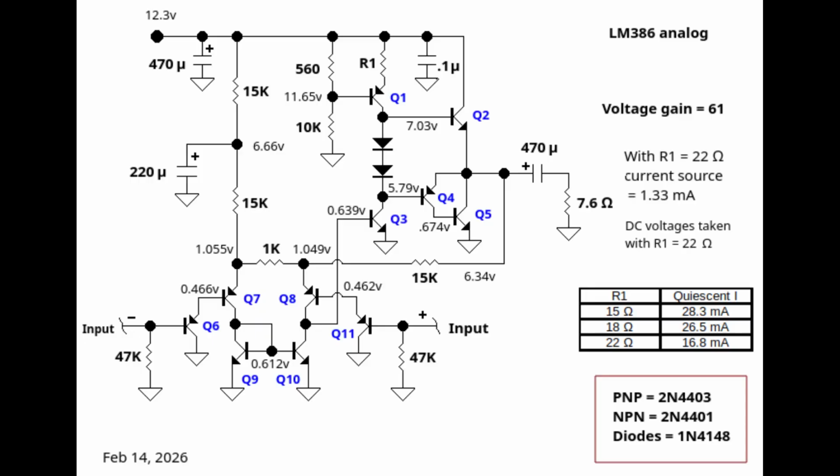Now, let's imagine if the diodes were not present, that the transistors were not forward biased slightly. Each final transistor will not turn on until the appropriate polarity AC waveform forward biases the transistor by about 0.7 volts. A positive going AC signal for an NPN transistor and a negative going signal for a PNP.